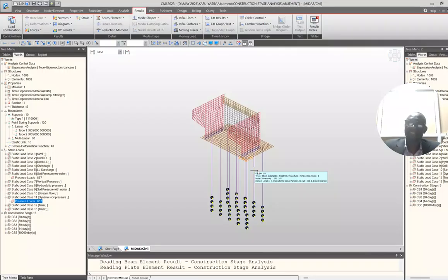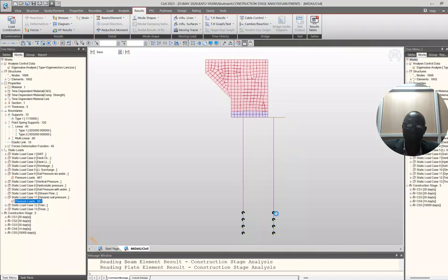You can have case one at the commissioning of the bridge, when you are done with the construction, the river training is done well, river bed invert level is still okay, therefore your spring constant is all the way up here. Then maybe after 10 or 20 years you can take a 5-meter scour, run an analysis, see the implication, then you run another at 50 years, and then when it is about 75, you do a complete one. So you look at the scenarios. Maybe at the end of it all, you look at the impact of the push-pull effect, the stability issues, and then you strike a balance. But I have just gone to the worst case scenario to have a look at this.